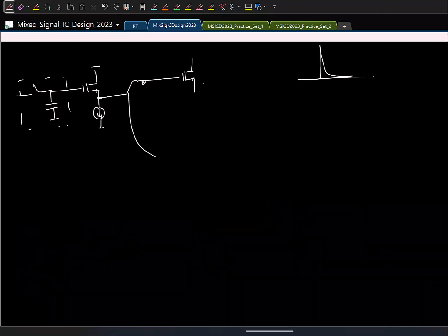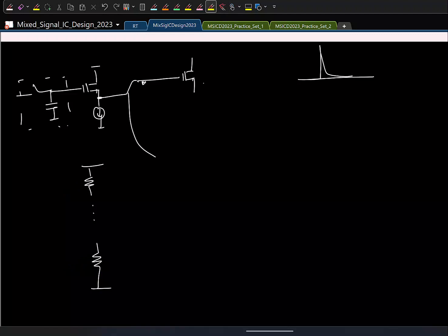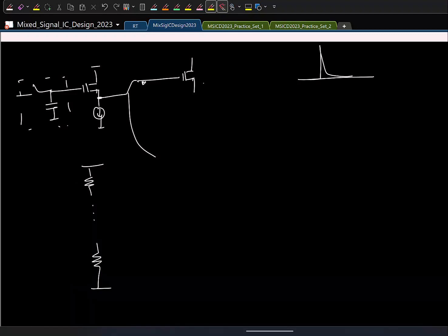Okay, I mean, I'm saying the simplest, one way if you are doing the reference subtraction in the voltage domain, you generate using a resistive ladder like this. Mismatch in the resistor, so you have to size them accordingly. That's all. I mean, the one nice thing about flash ADCs, you don't require very tight specs on linearity, right? For 6 bits, this much resolution can be obtained easily with a resistive ladder.